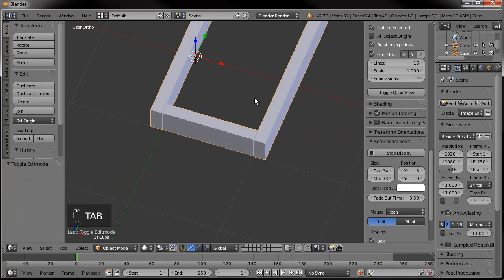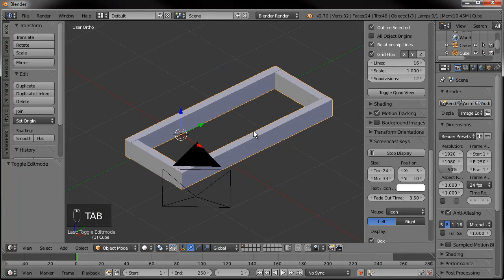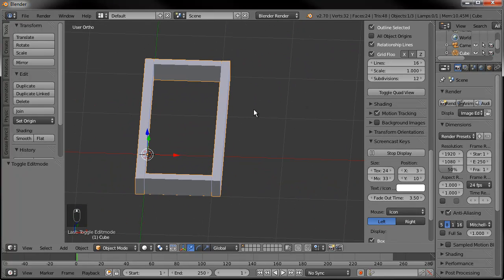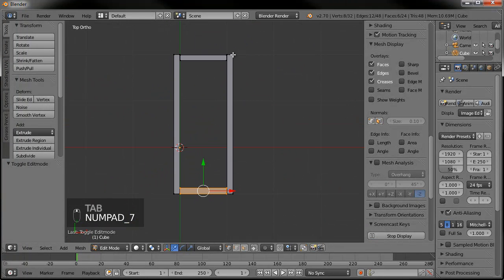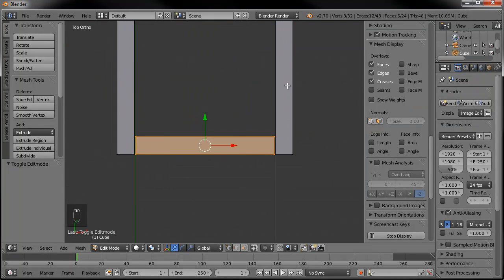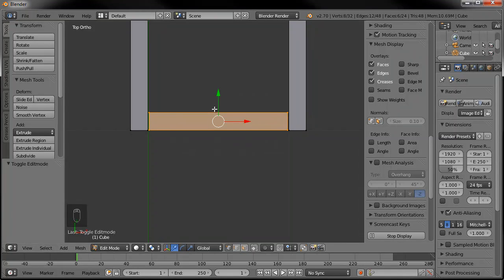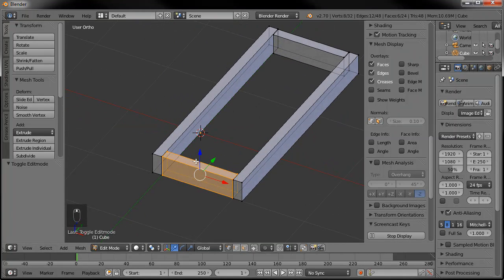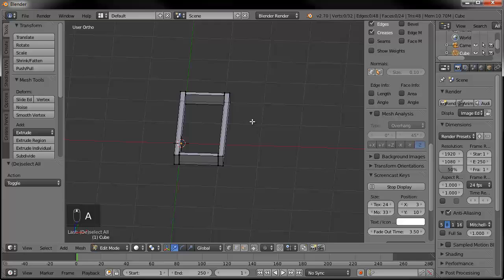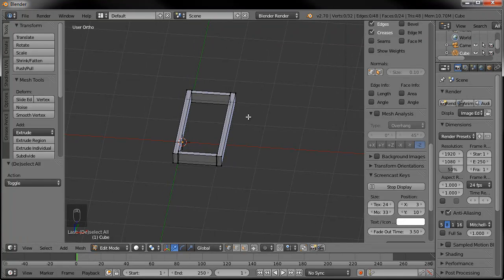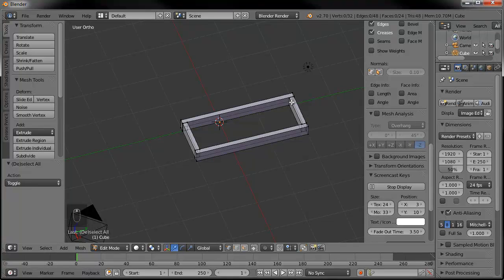And now you can already see this is going to help us out when we go to start cutting our wood, our actual physical world wood. We can see what dimensions we're going to need. So for the 2 longer boards, it's going to be 3 feet long. So that's easy enough. But then for these guys on the inside, I guess it'll be 1 foot because we're on the outside of the edge there. So we got 2 sections of 1 foot, and 2 sections of 3 feet. So we have essentially an 8-foot board right here. So if you buy a 2x4 by 8, it'll encompass all that you have here.